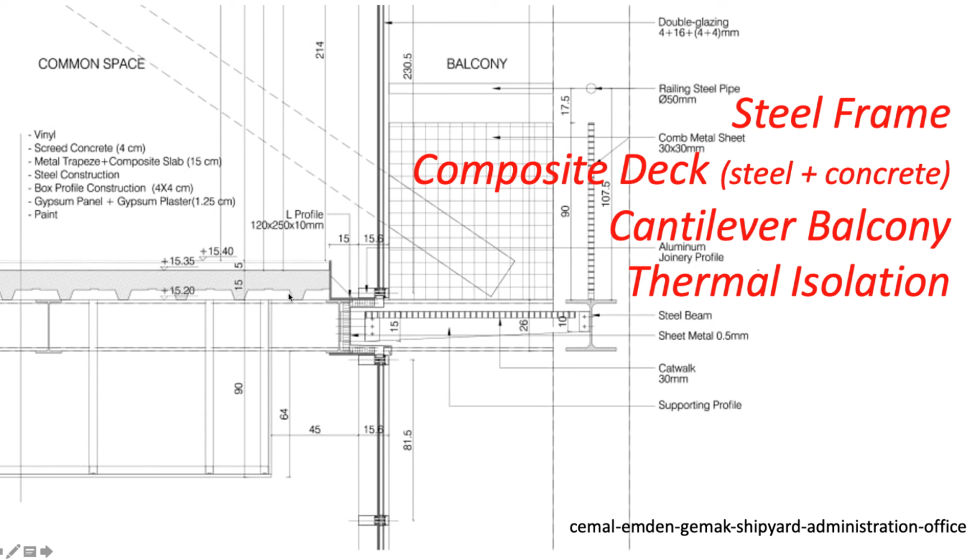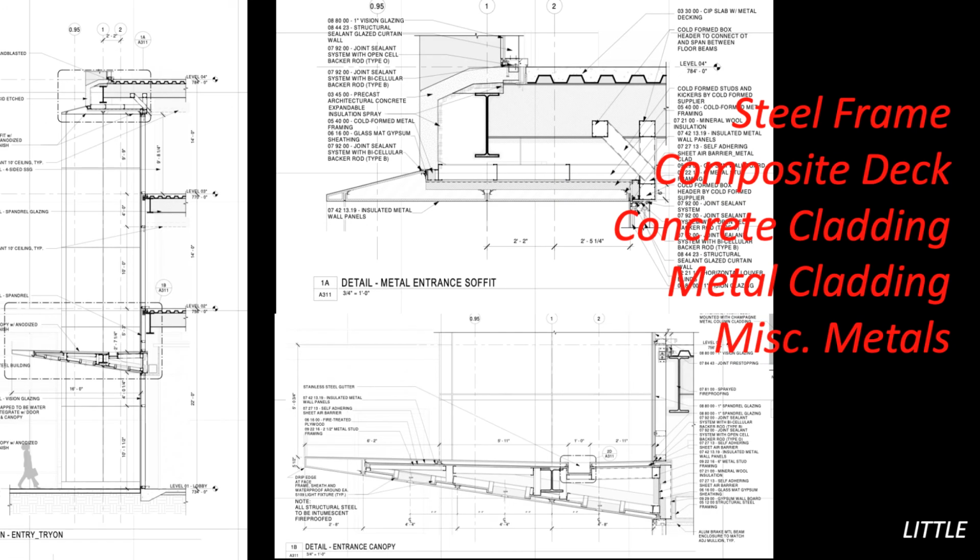Another way of creating this kind of exterior condition would be, if we had our decking changed in the opposite direction and we had these little ridges running this way, we could actually cantilever that composite deck up to about 10 feet in order to carry areas outside of the envelope of the building. So this is another wall section that I found useful because it also shows quite a few other kinds of conditions that you may have in your design.